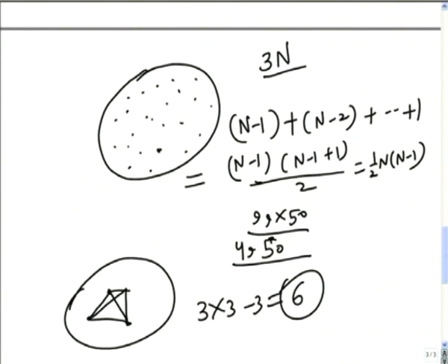So there are only 6 independent degrees of freedom. Now, if we fix a point O on the body and some coordinate system, then 3 coordinates are needed to specify the origin of the coordinate system. Since a total of 6 degrees of freedom are required to specify the body, 3 coordinates are needed to specify the orientation of the axes.